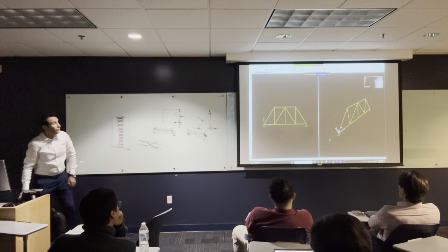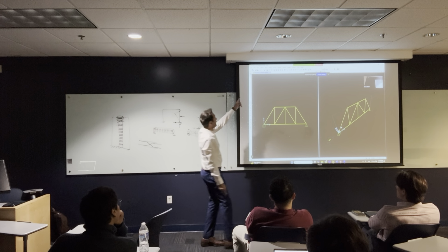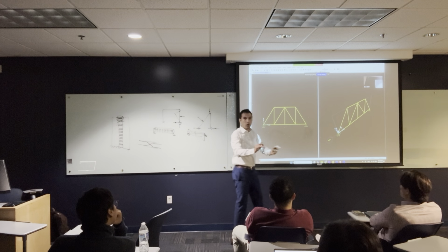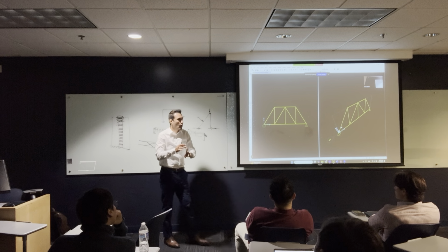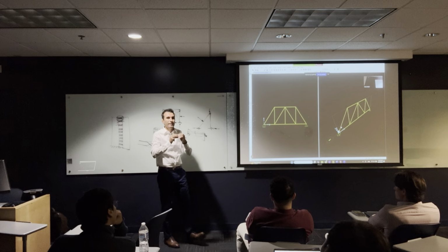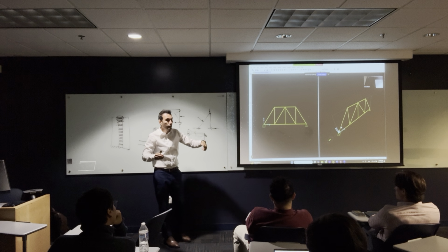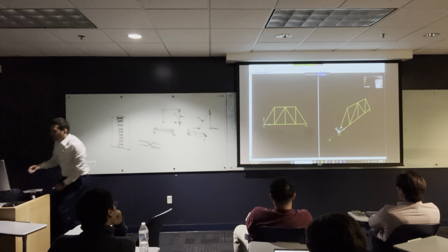Actually, it runs, and there's no bending moment. It says I'm showing bending moment M33. There's no bending moment. So we solved the issue of the hinges. We solved the issue of the bending moment. So that's right now a pure truss. It doesn't have a bending moment M33, moment about the 3 axes.